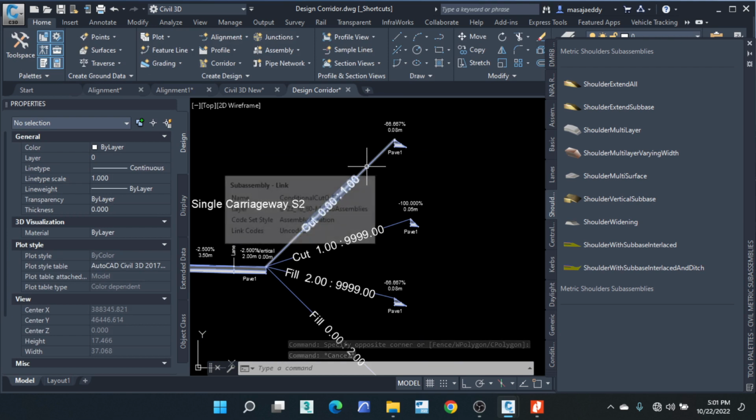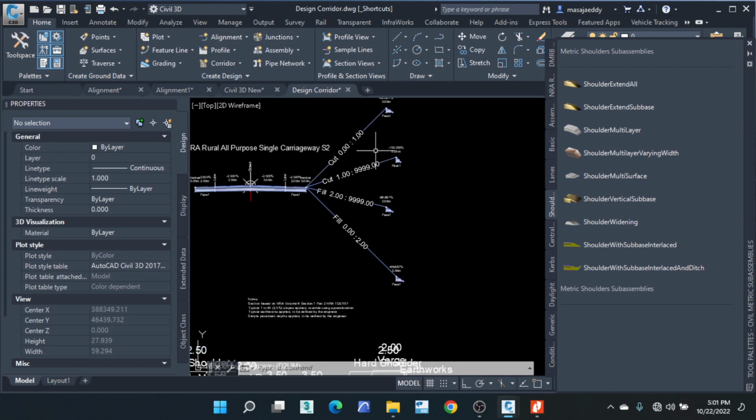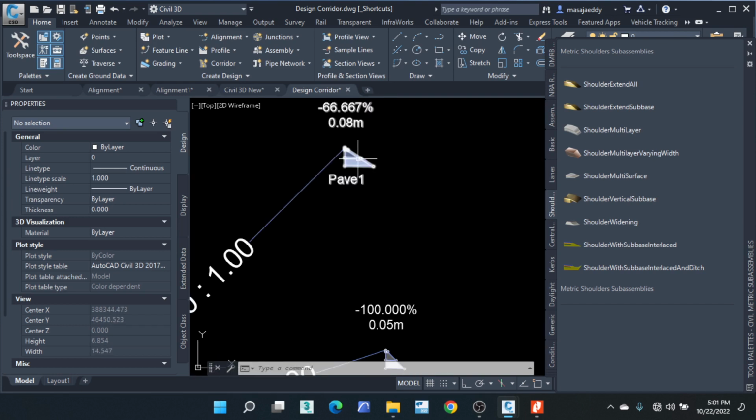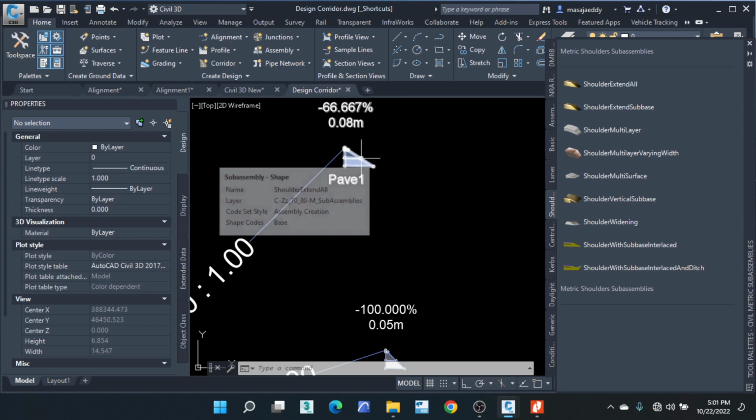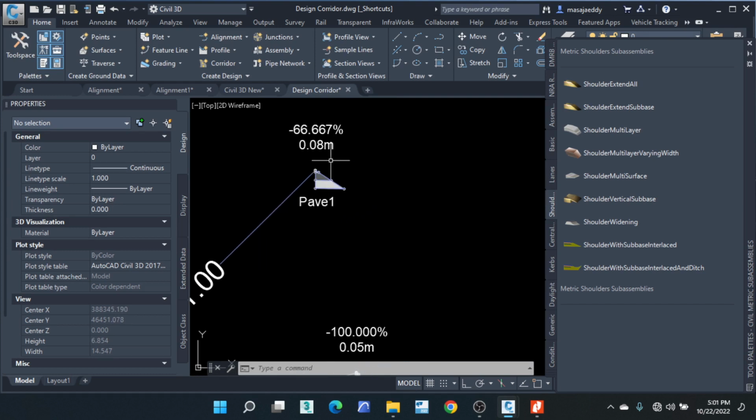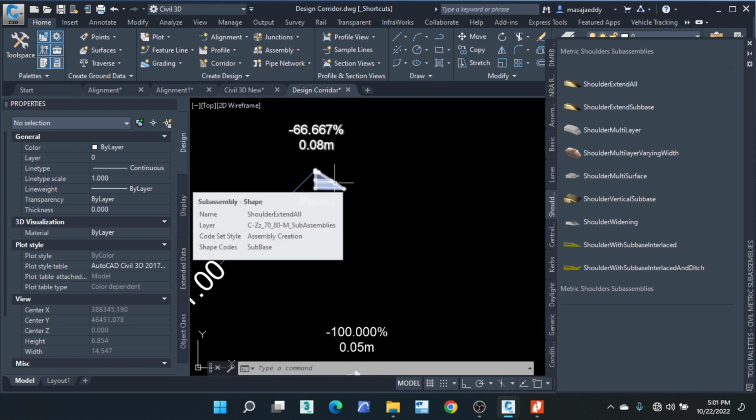Here, what we did is create conditions for cut and fill, depending on our vertical profile, on how we are going to be cutting or filling different areas. For a cut of 0 to 1 meter, we are going to use a cut slope of 1 to 1.5.